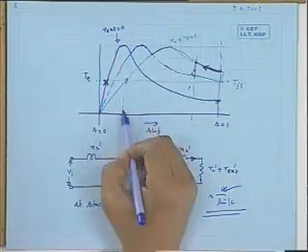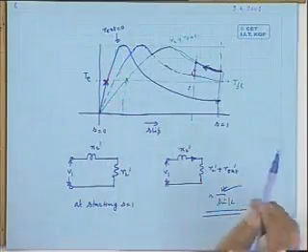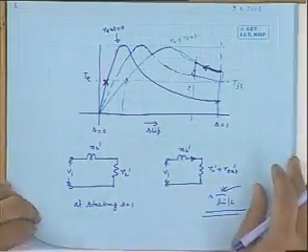Now, anyway, so there are some good points about connecting external resistance. Of course, one should not keep the external resistance connected all the time. Then there will be unnecessary power loss and the machine speed will also be lower. Okay.